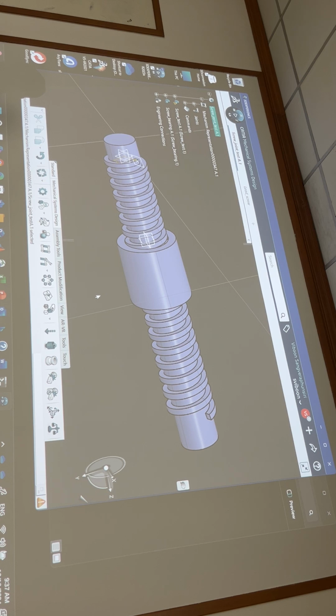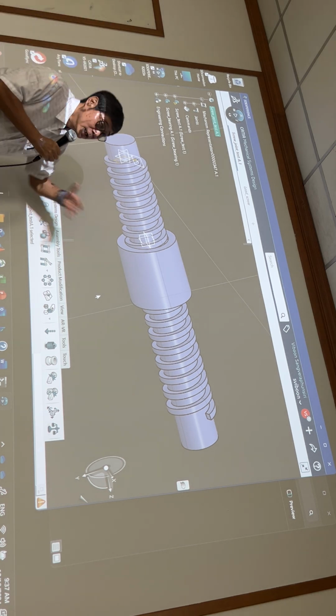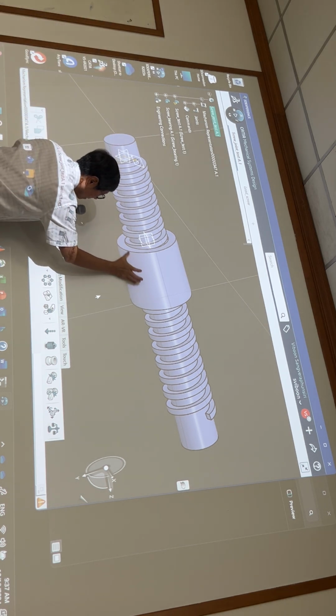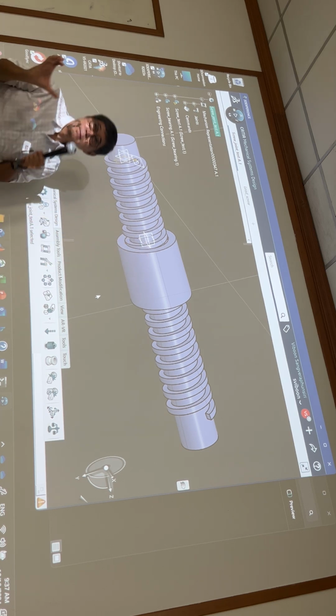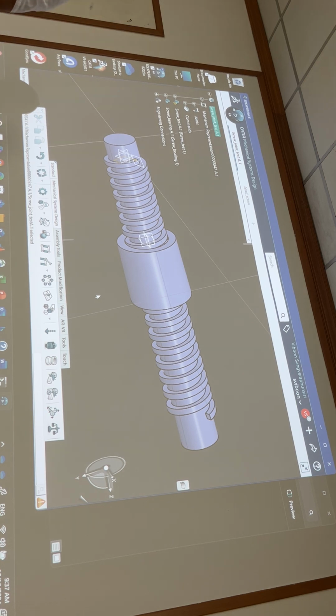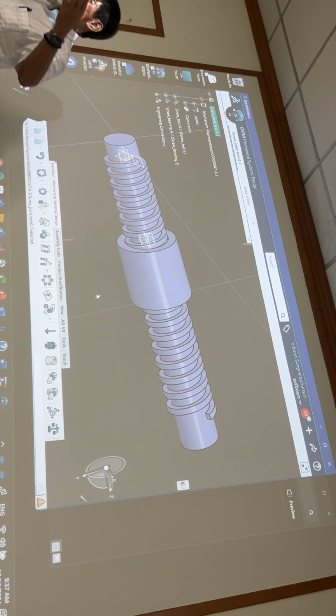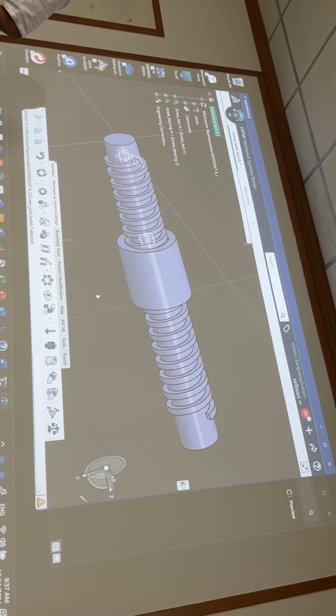8,000 baht. And they have many grades, based on precision, because sometimes you don't want backlash. If the balls are not good, there is a little play. If we design a machine that must maintain 5 micron, this one may cost you 20,000 baht instead of 8,000 baht. There are many grades, depending on the precision you select.